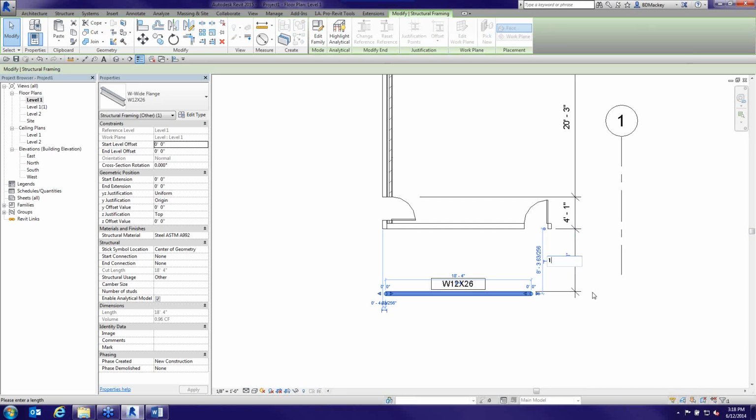Yep. And so the other thing I was going to say, if you are doing values, thank you, Rick, I can go 6 space 3. That's going to be 6 feet 3 inches. You could also do decimal fractions if you want, so 0.25 for 1/4 of an inch, 0.125 for an eighth. Again, I do it this way, except without the space, simply because I like to keep my hand on the 10 key. So all of that just works beautifully when you get there.